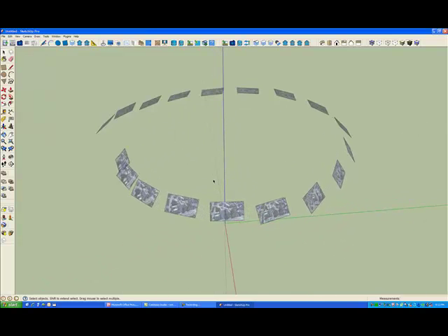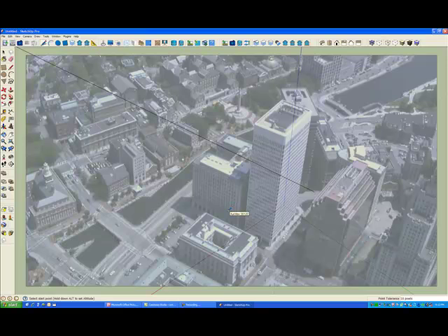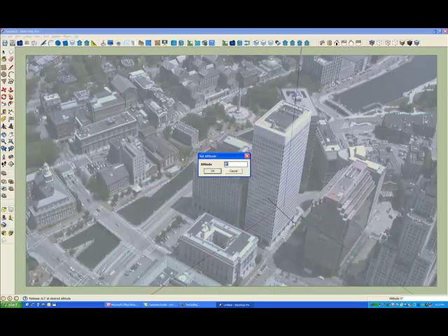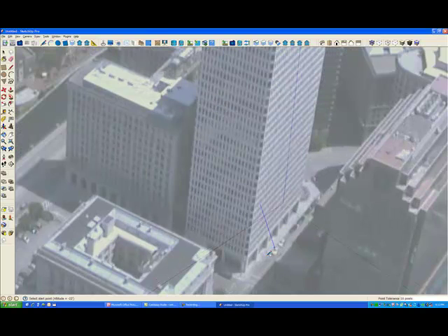When we're inside of one of the GeoSketch construction tools, then we also have the ability to use the arrow keys to flip between the images until we get to the image that we want. In this case, I'll use the rectangle tool, and I'm going to build the rectangular footprint of this building. There's a coordinate system associated with these oblique images, and in this case the street level is at -22 feet in that coordinate system, so I'll choose that as my working plane, and then I just select 3 points to define the rectangular footprint of that building.